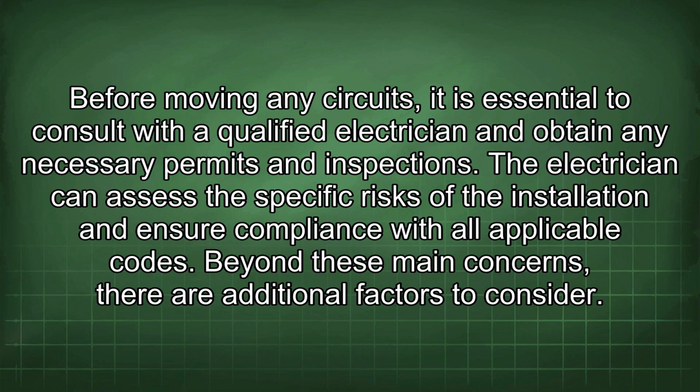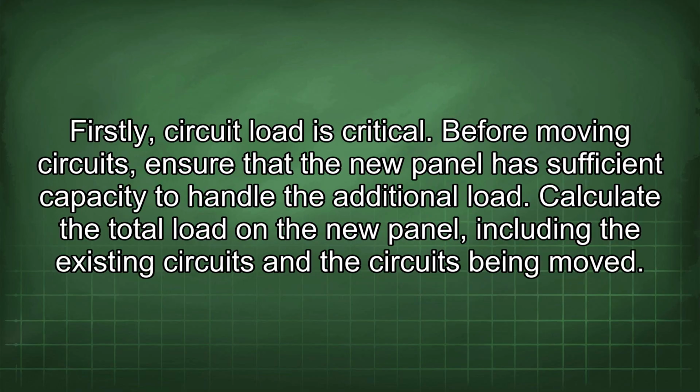The electrician can assess the specific risks of the installation and ensure compliance with all applicable codes. Beyond these main concerns, there are additional factors to consider. Firstly, circuit load is critical. Before moving circuits, ensure that the new panel has sufficient capacity to handle the additional load.